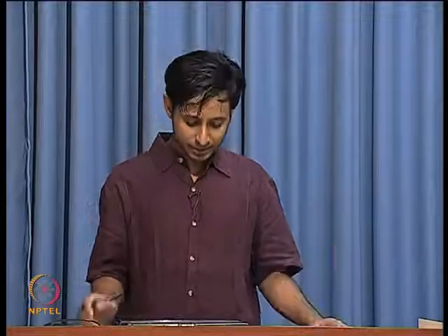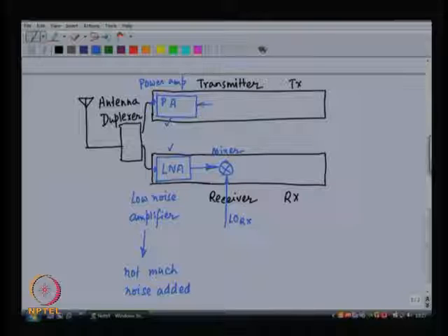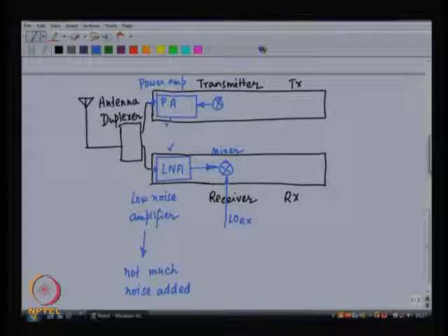What is going to happen right before the power amplifier? Something very similar. You do not want to work with high frequencies. So, you want to work with low frequencies as much as possible. So, the last block before the power amplifier is the mixer. So, LO stands for local oscillator. The local oscillator for the transmitter is typically different from the local oscillator of the receiver. You do not want transmit and receive to be working at the same frequency band.